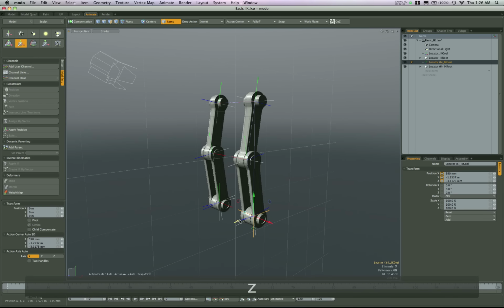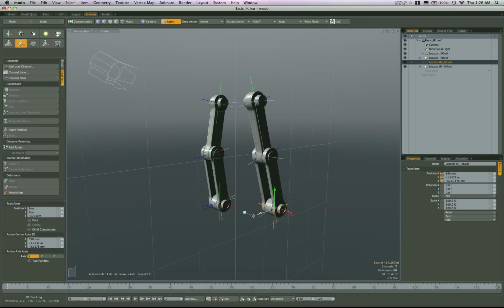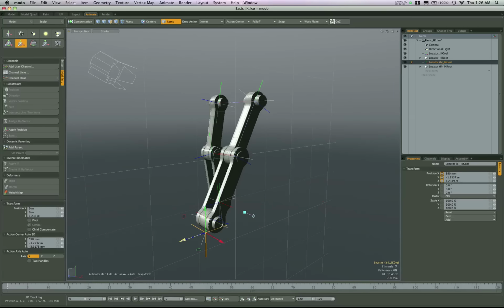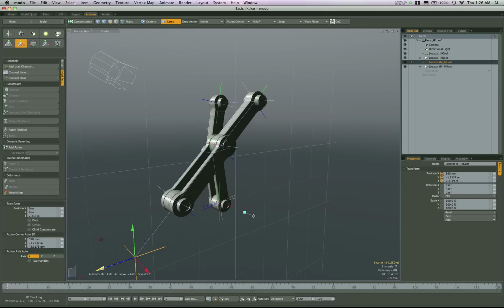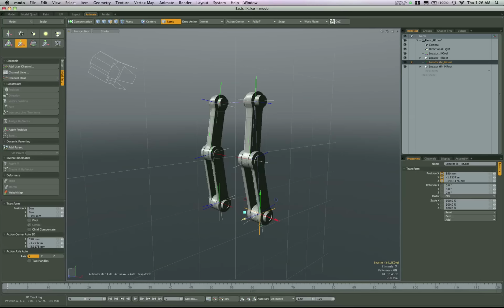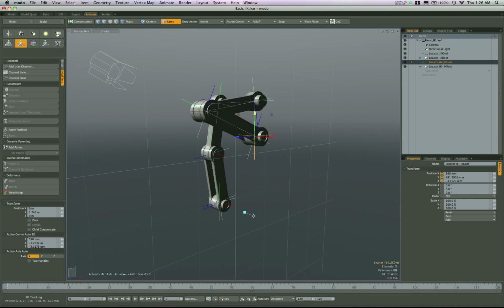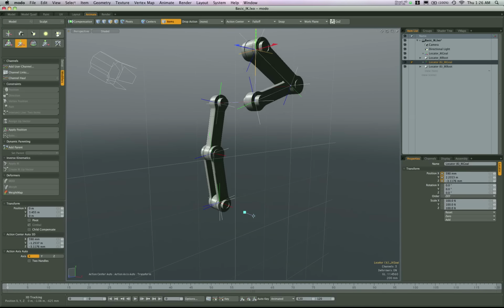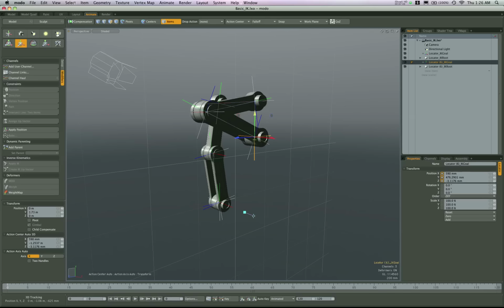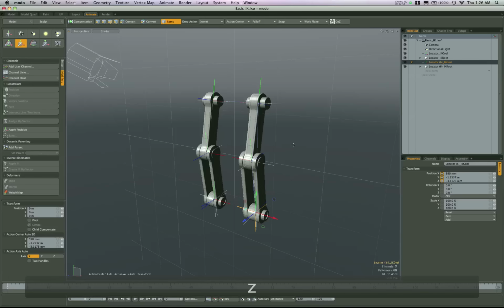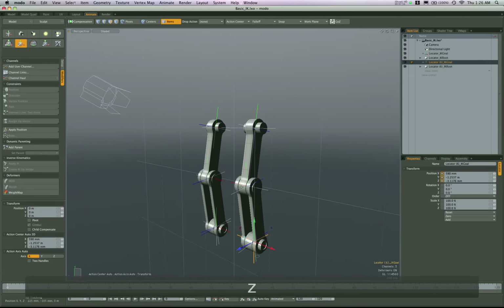But the locator goals now are going to give us the typical IK idea that we're looking for. I can move them up and down, left and right. If it moves beyond the joint, it's just going to stay oriented towards it and not do any bend. If I pull it up, it could go past it and invert it completely, but we haven't set up any constraints or anything for that. But this will allow us to get a typical IK setup off of these joints here.